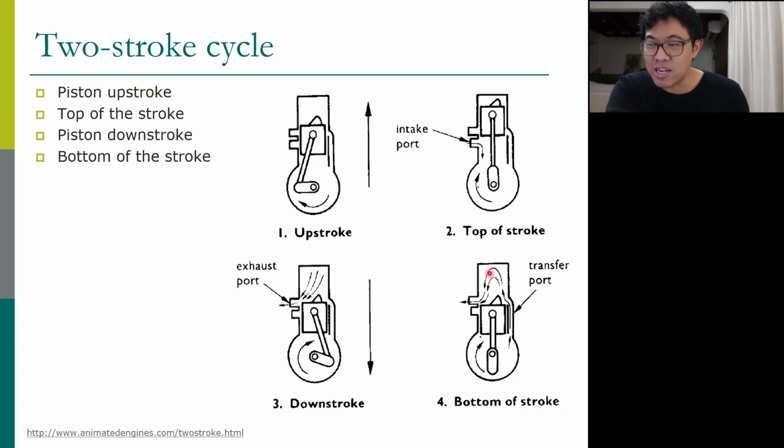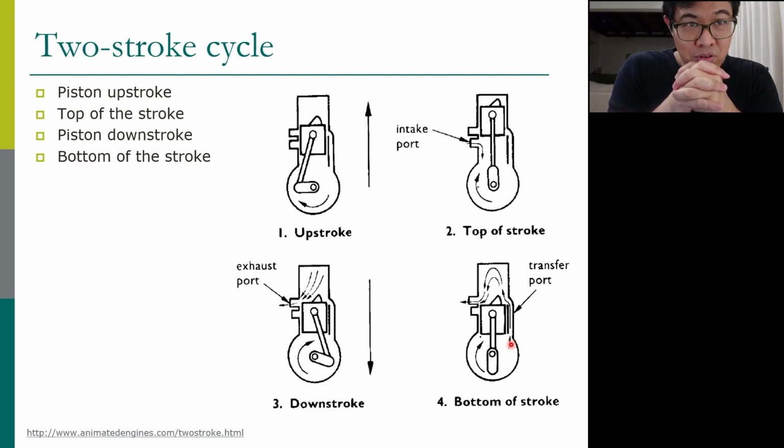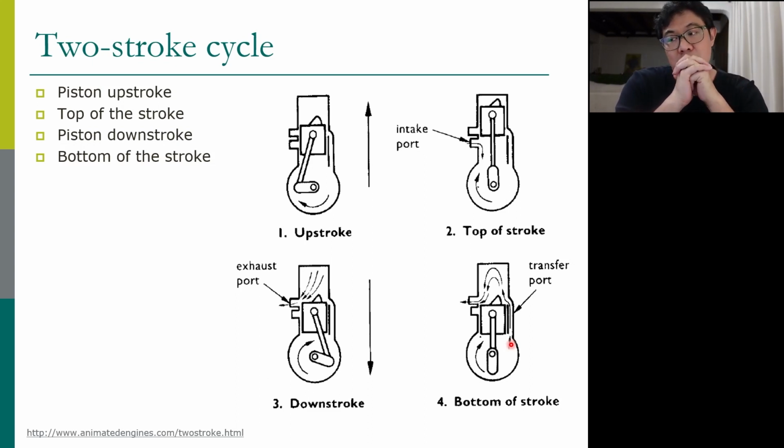So it's just like the exhaust going out, and after that a little bit of intake coming in, and then the piston moves up again. So during one stroke it does many things. It also uses the crankcase to store the air-fuel mixture coming in.